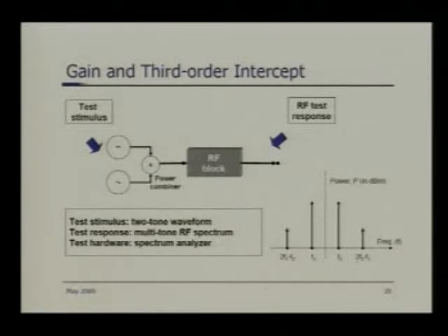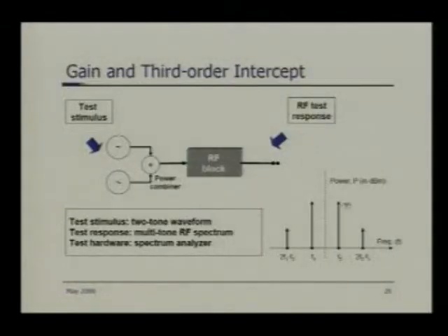But if the circuit is nonlinear, there will be an intermodulation between F1 and F2, and there will be other tones as well. So what third order intercept does is that it measures the amount of nonlinearity appearing in the form of this IMD tone. So if there is a specification which says that your third order intercept has to be, say, 30 dBc, it means that whatever power value you measure, actually 30 dBc is really too good for RF circuitry.